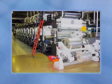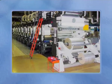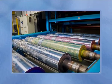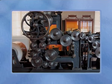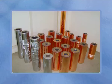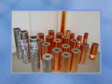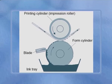Rotogravure consists of engraving the image onto an image carrier. In gravure printing, the image is etched onto a cylinder because it uses a rotary printing press. Gravure cylinders are made of copper-plated steel or aluminum that is engraved or etched and then chromed.